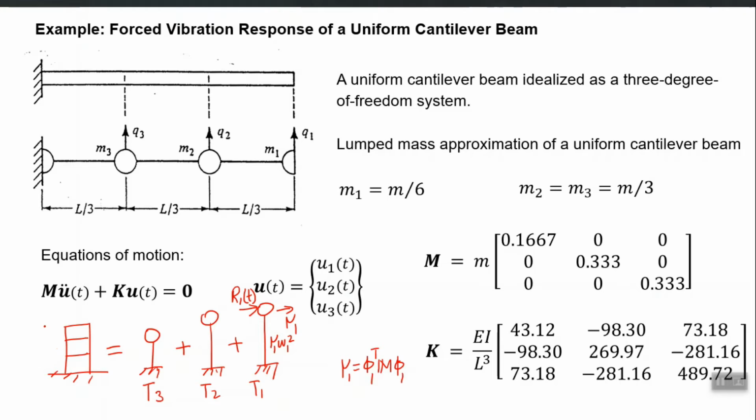So you apply any dynamic forces, a set of dynamic forces which is represented by the capital Q of t vector. You apply that vector to the actual multiple degree of freedom system, or you apply R1, R2, R3 to these modal SDF systems and sum their responses, you get the same response as when you apply that capital Q of t. So this is, let's say, applied with R3 of t. The relationship between R1, R2, R3 and the capital Q is this one, that the R vector containing R1, R2, R3 is equal to the capital phi matrix transpose times Q of t, right.